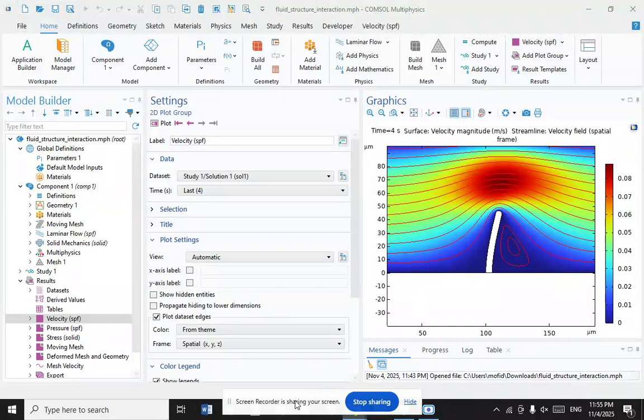And what are the approaches? Monolithic approach: the equations governing the flow and the displacement of the structure are solved simultaneously with a single solver. Partitioned approach: the equations governing the flow and the displacement of the structure are solved separately with two distinct solvers. The monolithic approach requires a code developed for this particular combination of physical problems, whereas the partitioned approach preserves software modularity because an existing fluid solver and a structural solver are coupled.